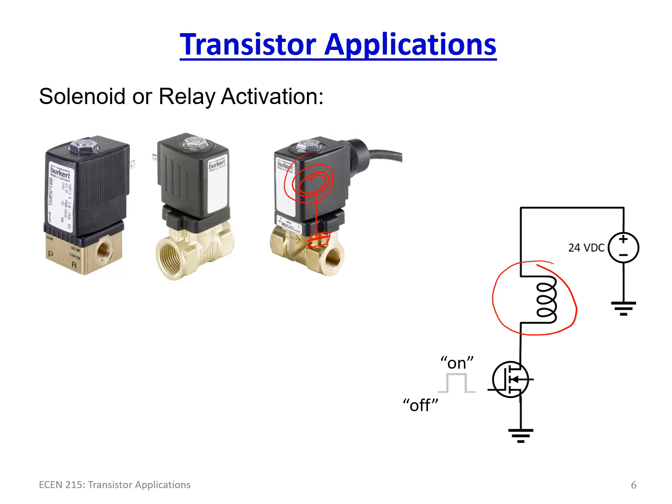And the way I would control this solenoid here is with a transistor. In fact, I used a 2N7002 transistor in this particular application where I use an NMOS transistor, where this signal here on and off was 3.3 volts here, and this was simply 0 volts.